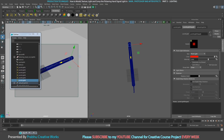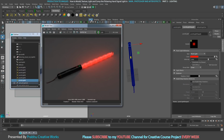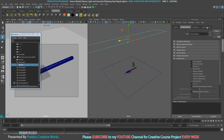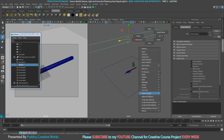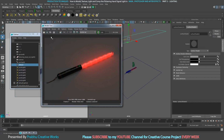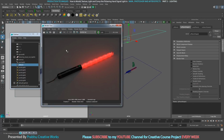So select our scene and click render. So we got our render. It's really cool, but I want to reduce the scene intensity a little bit. So I will select this surface over here, go to materials, right click and choose material attributes, and reduce the out color a little bit. So now I compare with my kept image and click render again. See, it reduces the intensity a little bit for us.